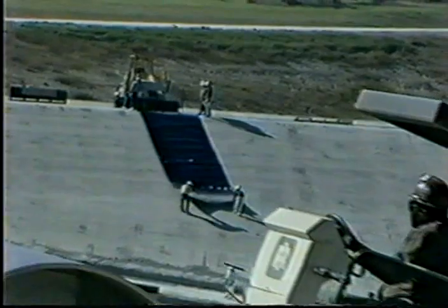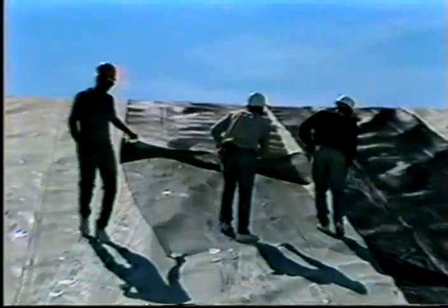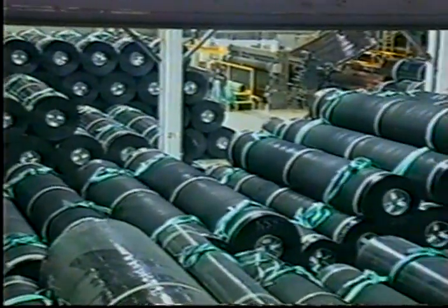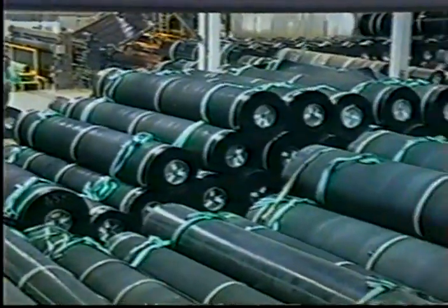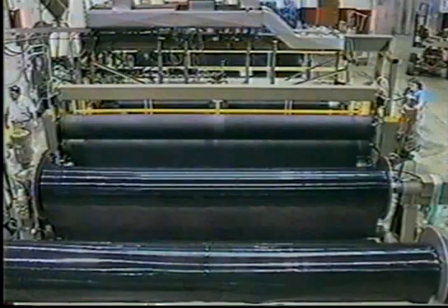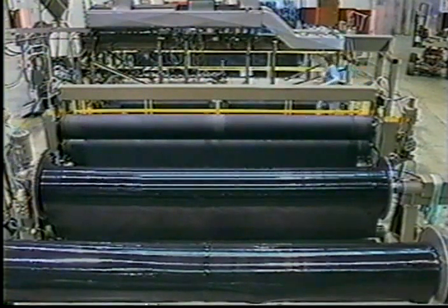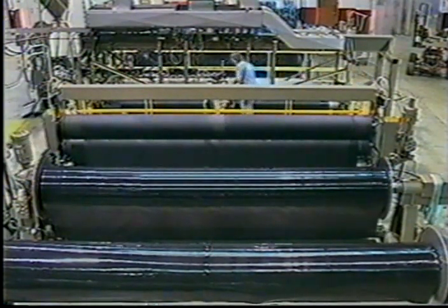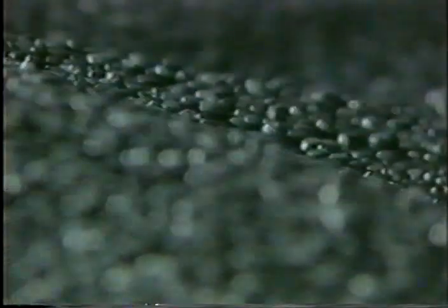Typically, geomembrane liners are low-permeability, flexible sheets made of various polymers. The most common materials are high-density polyethylene, HDPE, and PVC. Other materials are also used. Geomembranes are extremely durable. Most materials used for geomembranes include carbon black and other stabilizers which help protect them against degradation from light and heat.